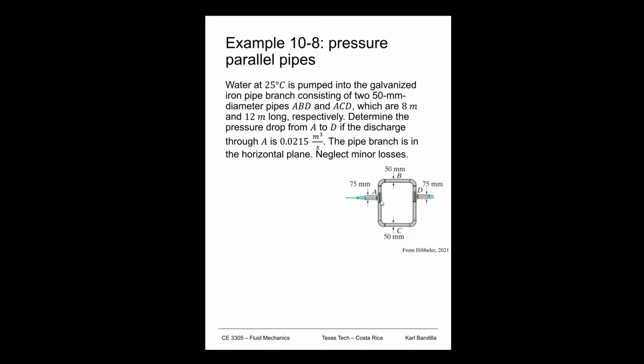Because the velocity of the water going through these pipes is going to impact what the major losses are, and of course those major losses are going to impact what the pressure change is going to be. So we'll have to come up with some iterative strategy. So to do that, we'll want to have a relationship between the velocity in those pipes and the friction factors, and so we are going to choose a set of friction factors and then start there. But to start out, let's figure out how we can get connections between the velocities and the friction factors.